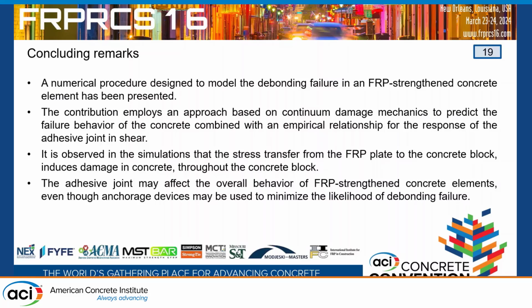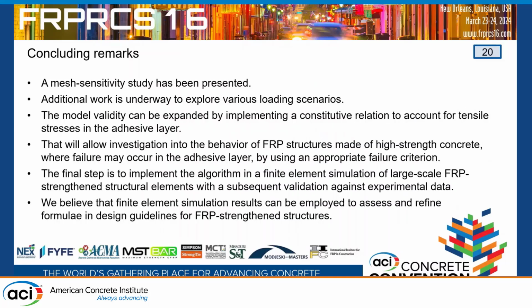It is observed in the simulations that the stress transfer from the FRP plate to the concrete block induces damage throughout the concrete substrate, and therefore the adhesive joint may affect the overall behavior of FRP strengthened concrete elements. So even though you are using anchorage devices, this should be checked many more times, but this is a takeaway anyway. A mesh sensitivity study has been presented,